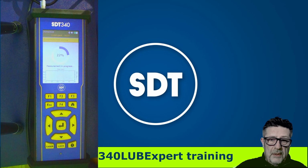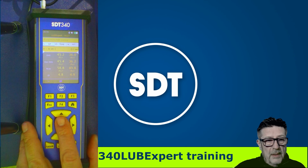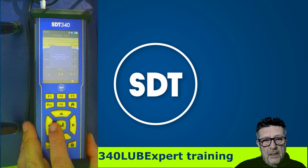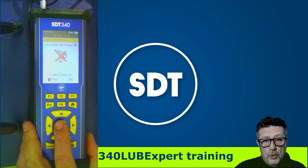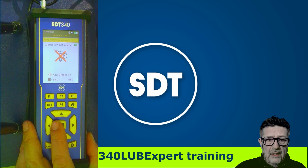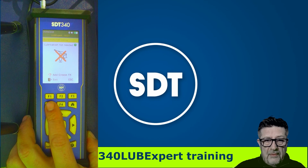And take the measurement. So now I'm taking the initial measurement. Don't forget, at this point I have alarm assigned. Here is my measurement. And instructions say do not lubricate, because there's no need. Alarm is not triggered. The signal is in a very low level. Now I would normally press escape, exit, and finish.